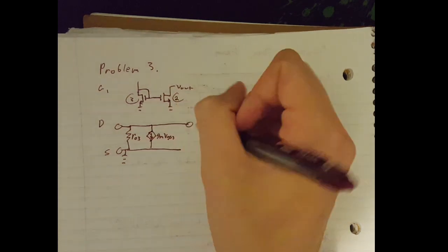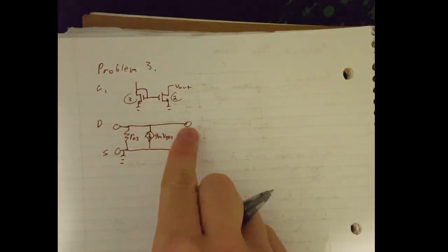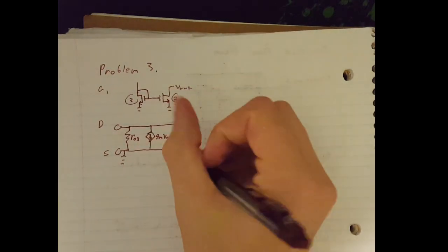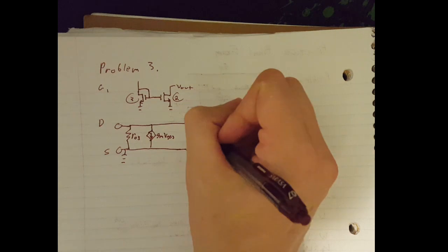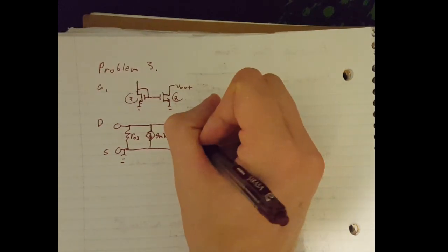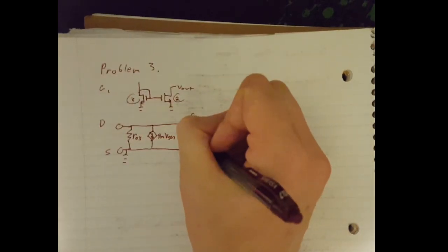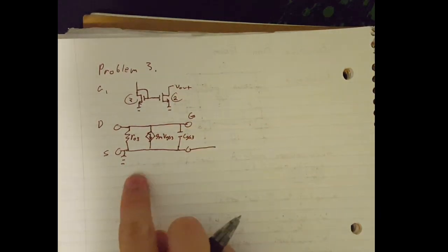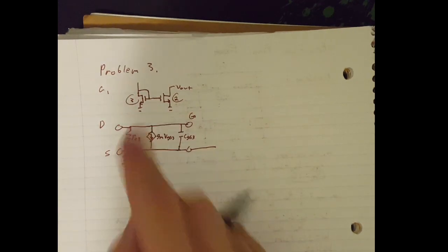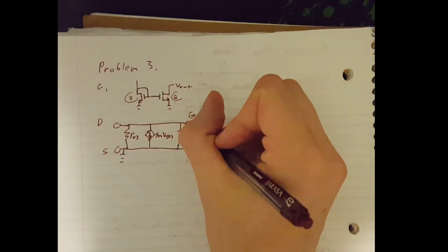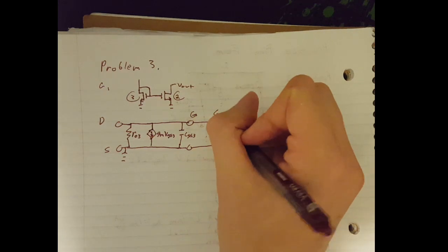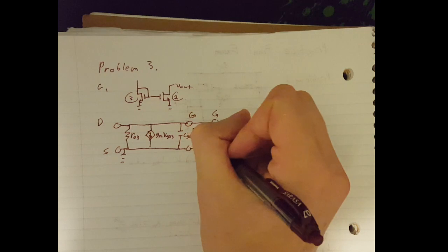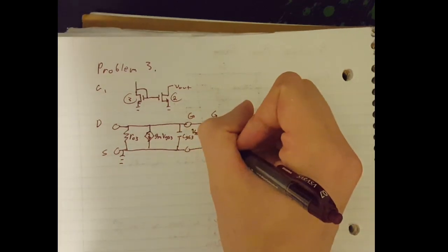This comes over to the gate over here. And you notice that I tied the gate and the drain together because it's tied together on the circuit. This is the gate G. This has CGS3. And I'm tying the sources of these together because they're both tied to ground. And the gates are tied together, so let's go over to this gate, G. And this is VGS3 right here, across this, which is equal to VGS2.